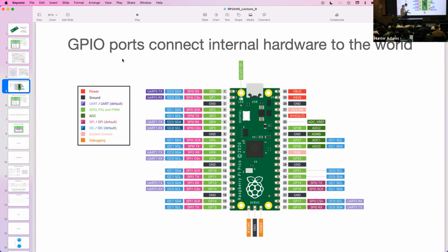But generally speaking, for most of the internal signals, you have your choice of a few. Which is nice because you may want to choose one GPIO over another GPIO because, well, perhaps you want to use GPIO 3 for the I2C1 clock line, so you use a different GPIO for your SPI0 transmit line, right? So you can sort of optimize which signals are getting mapped to which GPIOs.